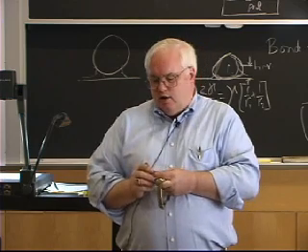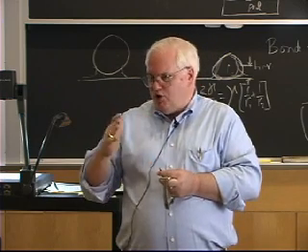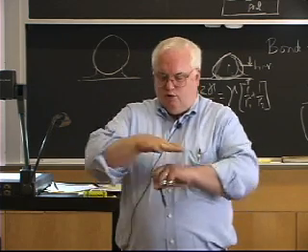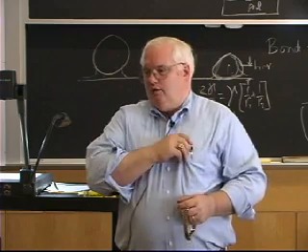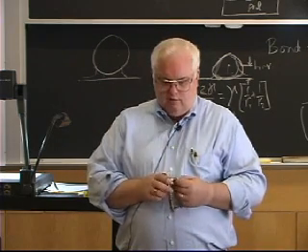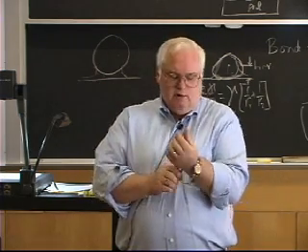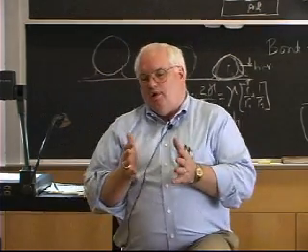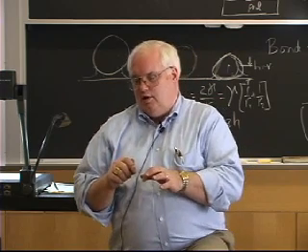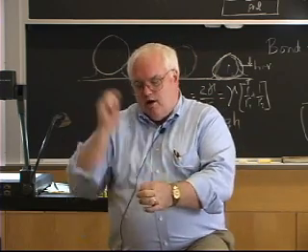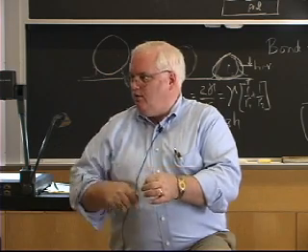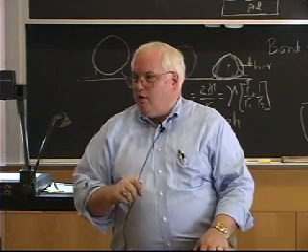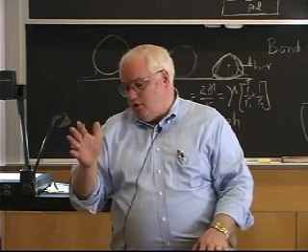He couldn't buy a wire, and ordinarily when you make a ball like that, you just buy a wire and chop it up into right circular cylinders, and then you grind it down into a sphere between two flat grinding plates. I said, well, I can do that for you. He said, how? I took him across the road to the same electron beam unit where I had melted my wife's platinum iridium engagement ring. I took a ball bearing and whacked a piece of copper block with it using a hammer, made a little somewhat spherical indentation, and put some of the powder in there. I put it in the vacuum system, put the electron beam over it, and melted it.